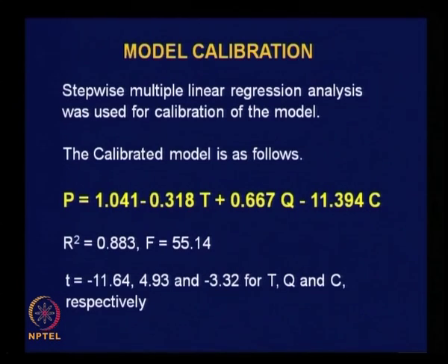What is your comment about the logical correctness of this model? You have some plus and minus signs. More the travel time, less will be the demand for a particular mode. See, travel time will have a decreasing effect on the dependent variable. Travel cost also will have a decreasing effect on the dependent variable, right. Since we have a dummy variable taking values of 0 and 1, it should naturally have a positive sign. So we can say this model is both logically as well as statistically sound.